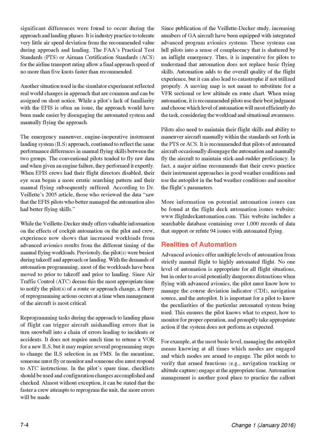When FE's crews had their flight directors disabled, their iScan began a more erratic searching pattern and their manual flying subsequently suffered. According to Dr. Villette's 2005 article, those who reviewed the data saw that the FE's pilots who better managed the automation also had better flying skills. While the Villette-Decker study offers valuable information on the effects of cockpit automation on the pilot and crew, experience now shows that increased workloads from advanced avionics results from the different timing of the manual flying workloads.